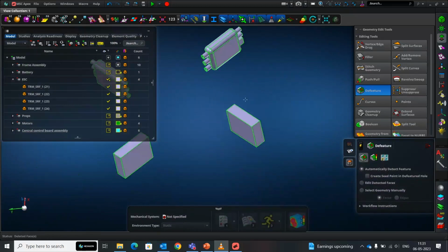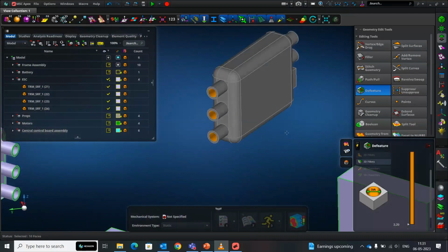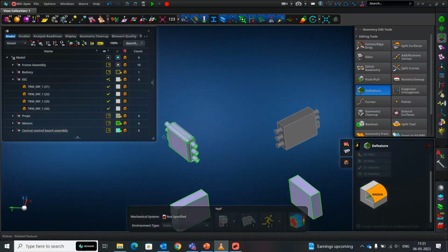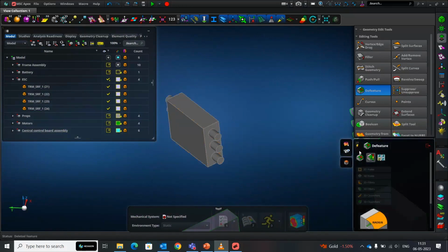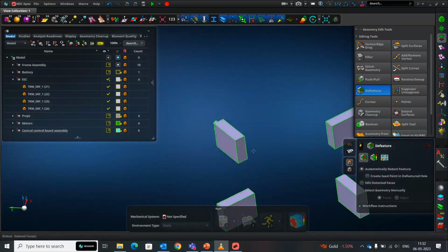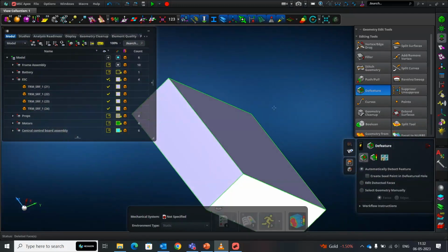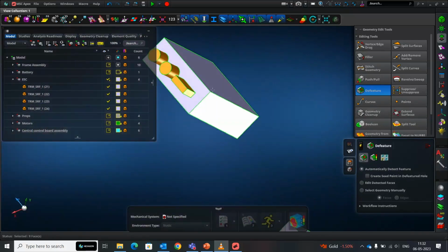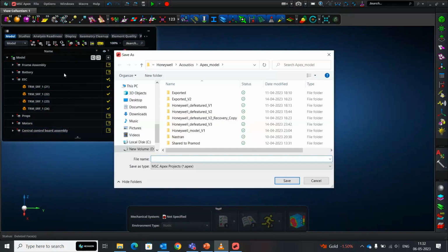So you can see here each of these steps quite easily simply by clicking. You can also see how we can eliminate these by selected feature. I can select the holes and then remove them. I can select the fillets, remove them. Similarly, for this one also, I'm selecting the holes, eliminating them, fillets, eliminating them by the middle mouse button. And simply choosing the external sleeve components that were remaining and eliminating them, such that I have blocks which would represent the mass properties which I'm going to apply to this. So you'll soon see where this becomes a benefit.